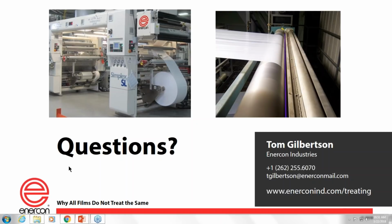This is a question back to thickness of material. If there's not a relationship to the watt density, if I run the same watt density on a film that's 0.5 mils and 20 mils, should I see the same results? If the film is the same, yes. So for example, what's the range we have here? 5 and 20. 5 and 20, yeah. So if I had 5 mil polypropylene film and had the same additive or color additives or whatever package is in there at 5 mil and at 20 mil, and I ran the same watt density, I should get the same result.